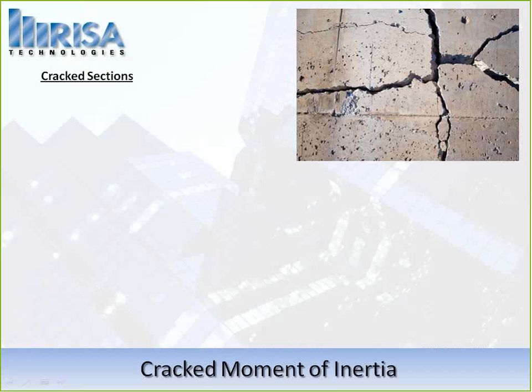The other piece we're talking about now, also stiffness, is cracked sections. So in your walls, we're going to want to apply some cracked sections for your deflection calculations. That's the only place where cracked sections are actually applied: it changes the moment of inertia to be for cracked. We can use gross or cracked.